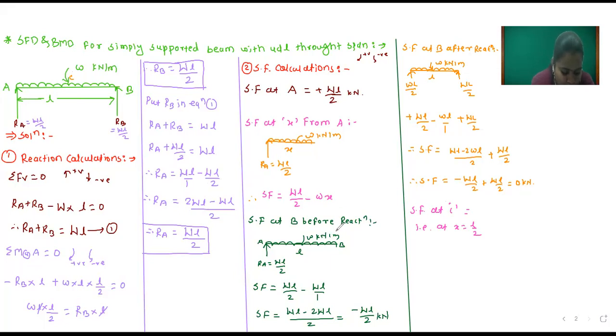So shear force at C, for this only that much load, WL by 2, and here UDL W is applied over a span of L by 2.